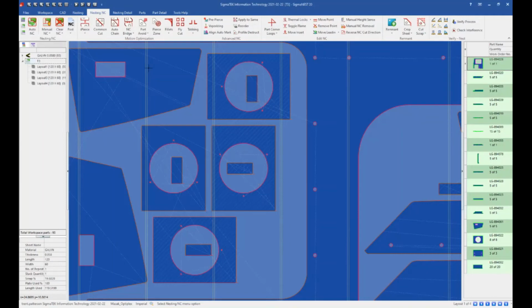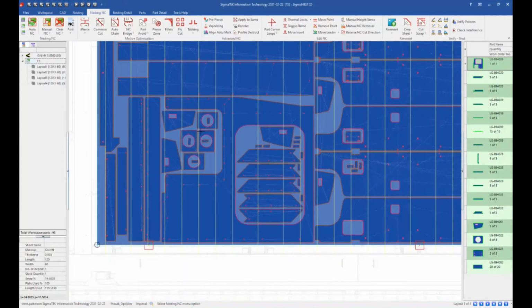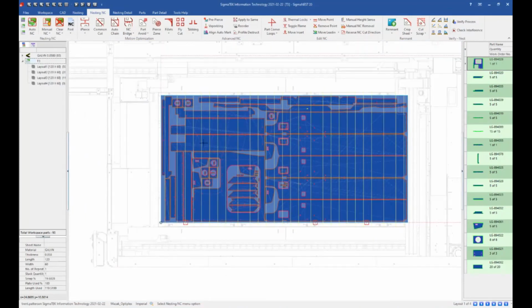You can use it with various other tabbing methods, kind of like we were going over. So you have the part removal or the tab removal, you have the recess tabbing, you have the different tab types, you have the center of gravity tabbing. So it is one of those things that definitely can be beneficial for you. With center of gravity as well, you want to make sure that you do have a machine bed drawing just so it knows where the slats are exactly, to make sure that it can look at the slats and know where tabs actually need to go whenever you're combining the two.